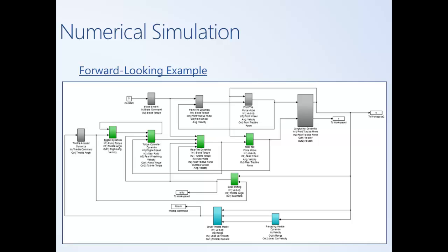So this signal could generate a signal to an actual physical piece of hardware. It can cause the engine to move, and then you could have a sensor measuring the speed of the engine or the torque being generated by the engine, and those sensor readings could then be supplied to another mathematical model. So this forward-looking architecture is very nice for hardware-in-the-loop testing.